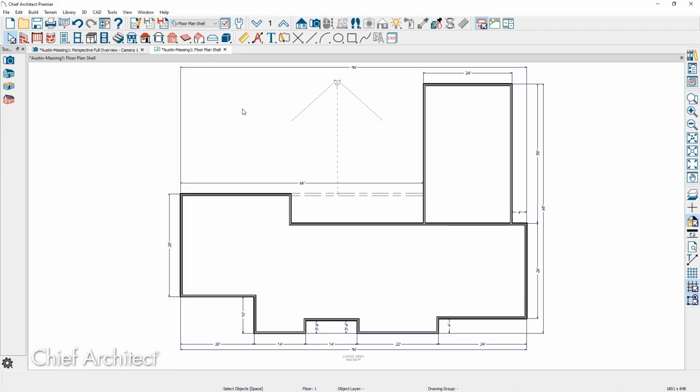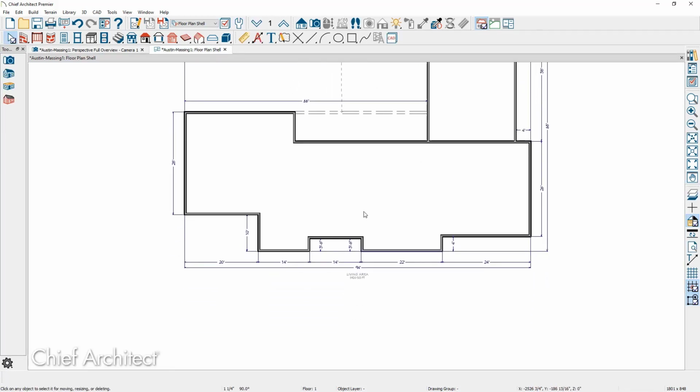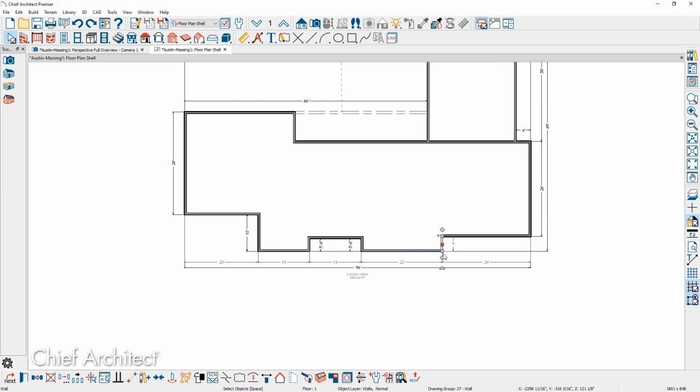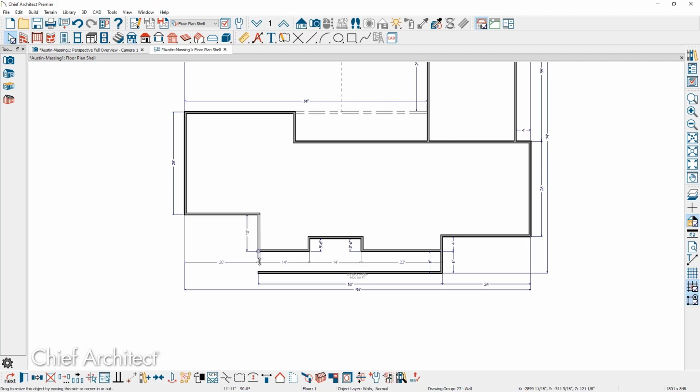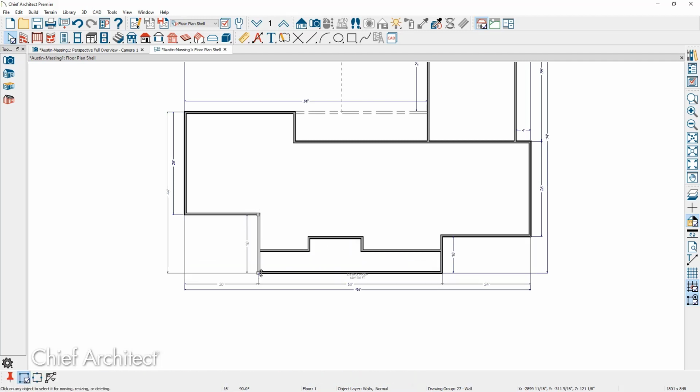Let's go back into the floor plan. I want to put a covered porch on the front side of it, so I'm going to extend the walls and then we'll also toggle them to be invisible. So grab the side wall on this side, pull this down, then I'll use the diamond at the end, pull that around, and we'll do the exact same thing over here. Use the number 3 on the keyboard for the break command, click an intersection in this area, click on this wall, use the break command. I'm going to hold my shift key down and we'll grab all 3 walls and toggle those to be invisible.